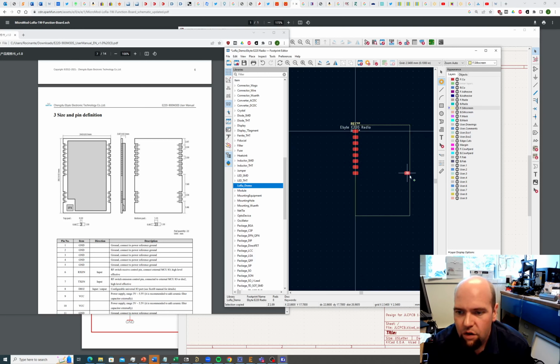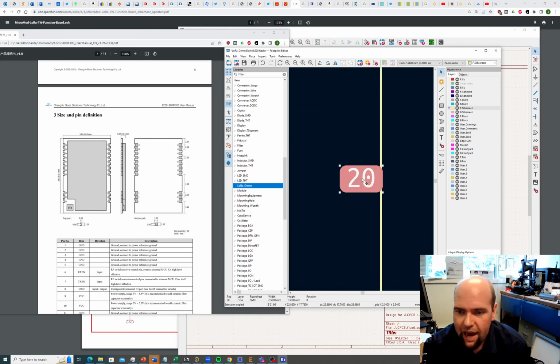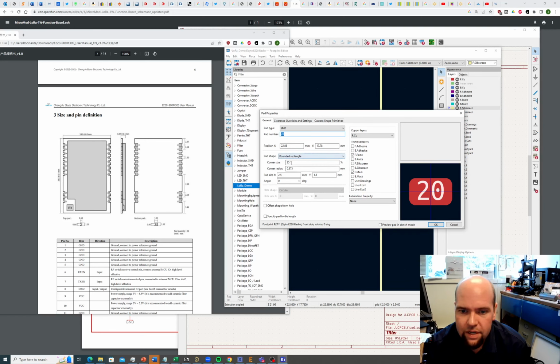Before I do that, I'm going to go over to the other side because these pins should be automatically spaced correctly now. So the other side starts at 4 down here. You see, my grid space doesn't allow me to hit it right on the edge, so I don't really care. I'm just going to place it so it's lined up vertically. I'm going to place that, and I'm going to go into this pad and specify that the X position now, it's a 24 millimeter wide board, so this X position needs to be 24, to be centered on the other edge of the board.